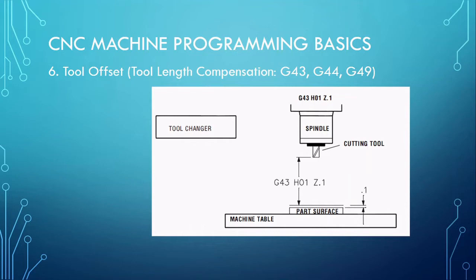because for the z-axis, going into the workpiece is negative Z, and going away from the workpiece is always positive Z. Because the datum tool has been used to set the 0 point, putting in a longer tool now, which will not make the Z-axis go as far down as the datum tool, will be a positive tool length compensation.